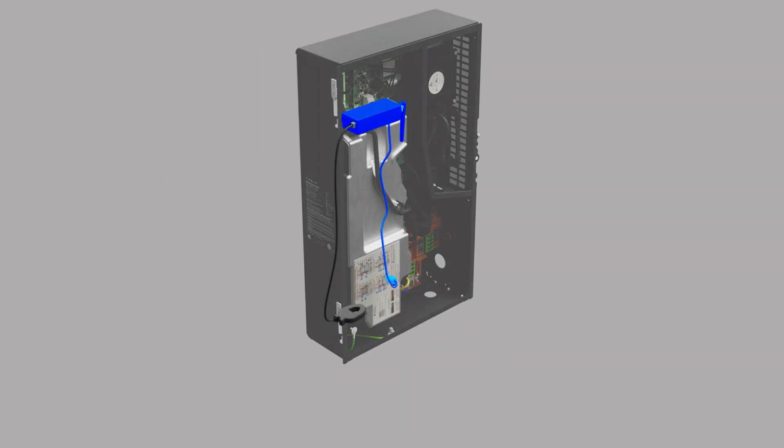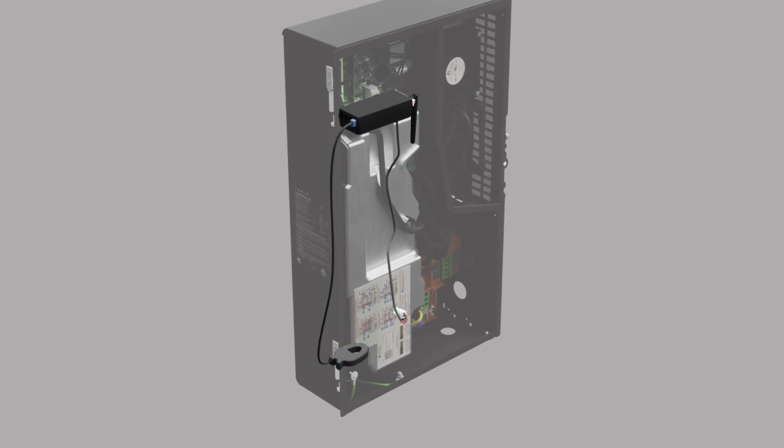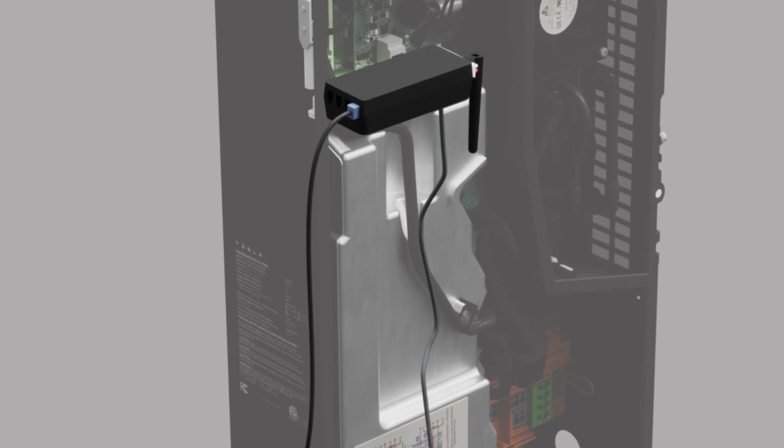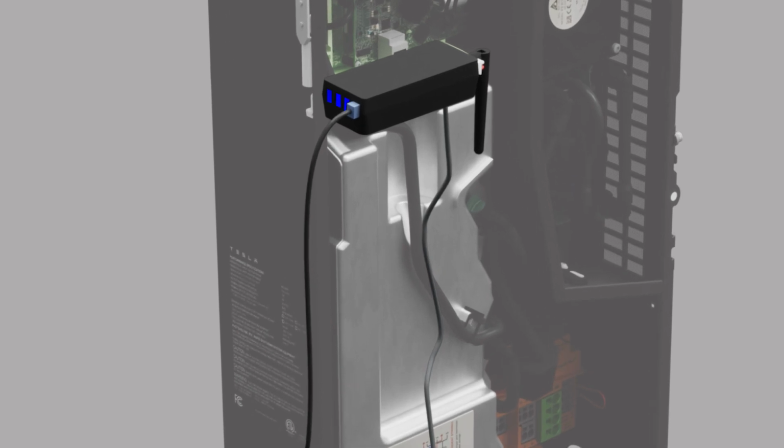To perform revenue-grade metering, one energy meter and one current transformer are factory installed within the inverter to monitor solar production with even greater accuracy than the inverter's internal metering. With the factory-installed current transformer plugged into port 1, the three remaining empty ports on this meter can be used for site monitoring. Installers have the option to use the empty ports on this meter or install a new energy meter for the current transformers used for site measurements.